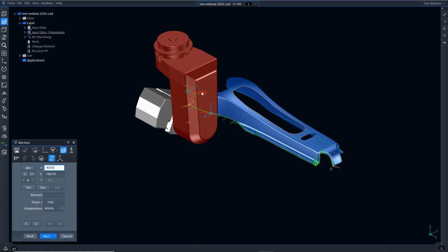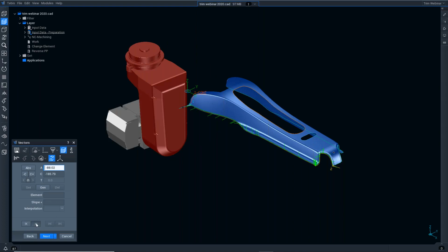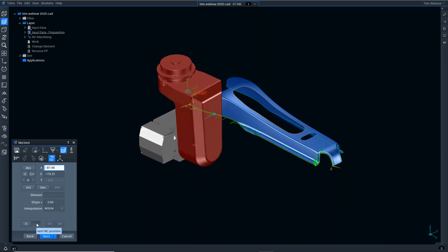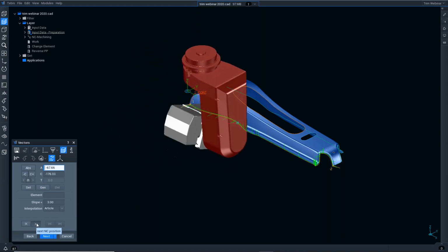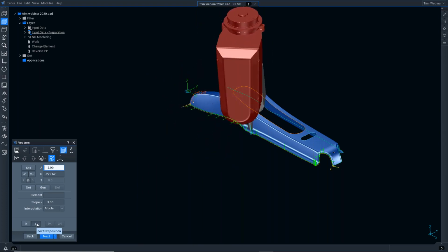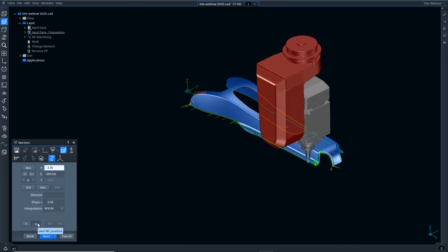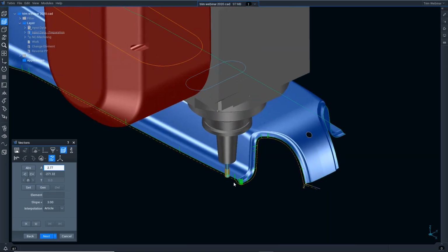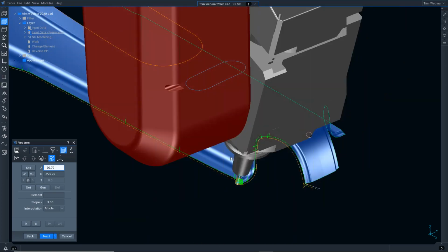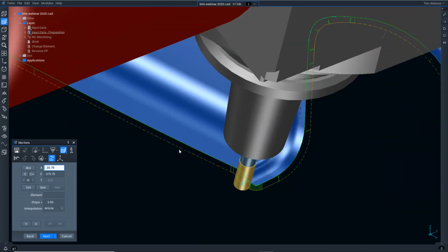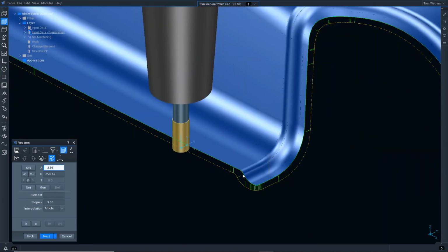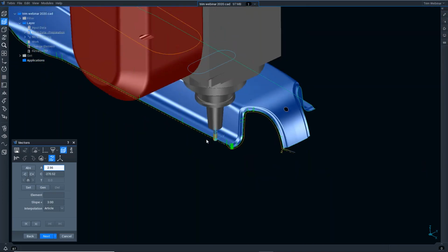Okay, so if we take this toolpath from the beginning and drive this through manually, what we can see is as the tool comes around and comes up towards the vertical position, we start to get an unwind. As the tool then traverses down the long area, when we get into this corner, what we find is that we have a vector off at an angle, and this will cause the head to roll over. Now, the vector is in exactly the right position because we told the tool to stay perpendicular to the surface. But what we need to do is program this angle out so that we don't have to have the head tipping over with excess movement.